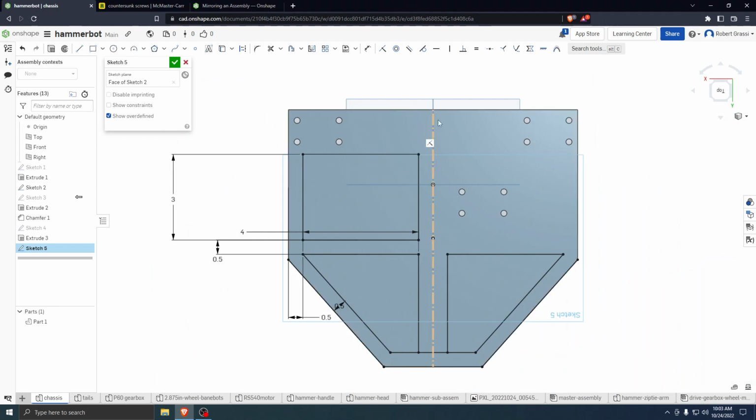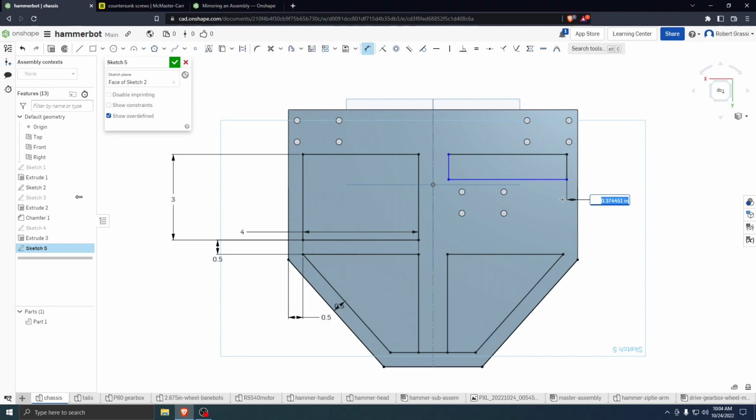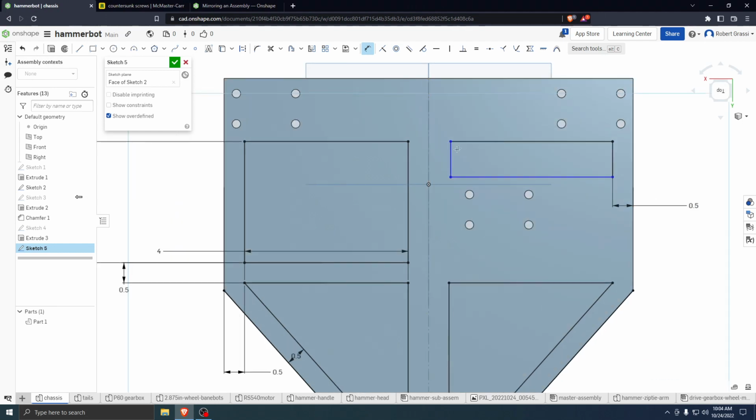Let's leave the back part alone because we know we're going to have the tail piece of the robot back there, with the wheelie bars. So let's put in another pocket, maybe right here. Yeah, that's good. And we'll have this beam thickness be 0.5, and we'll have this be, I don't know, 1 inch apart.